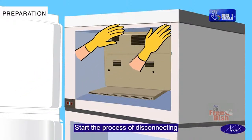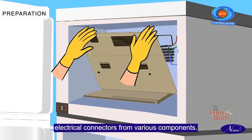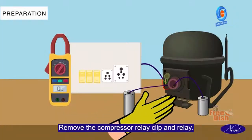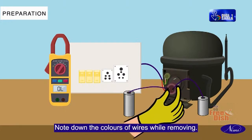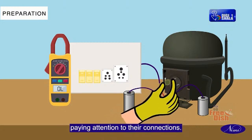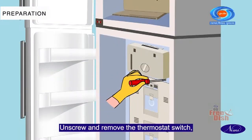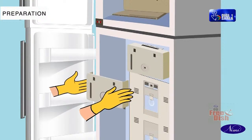Start the process of disconnecting electrical connectors from various components. Remove the compressor relay clip and relay. Note down the colors of wires while removing. Remove the relay wire and junction wire, paying attention to their connections. Unscrew and remove the thermostat switch, noting its position and connections.